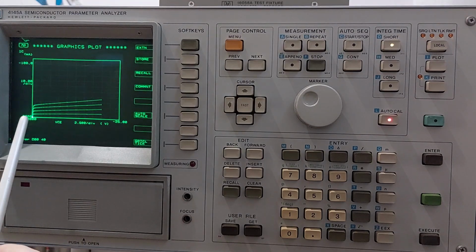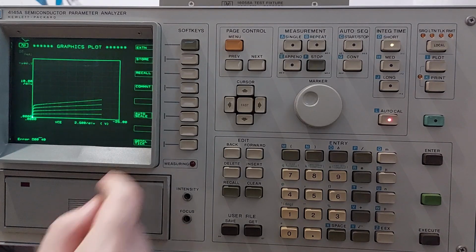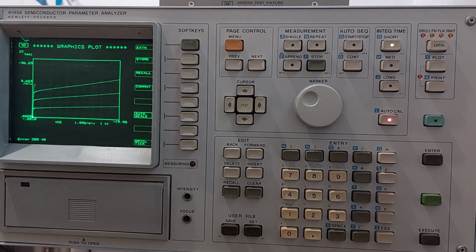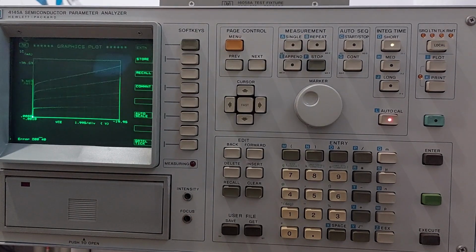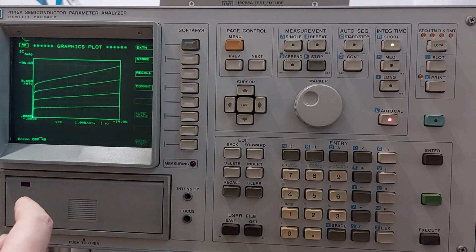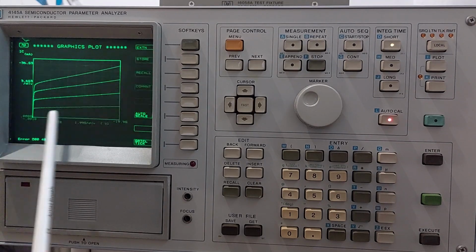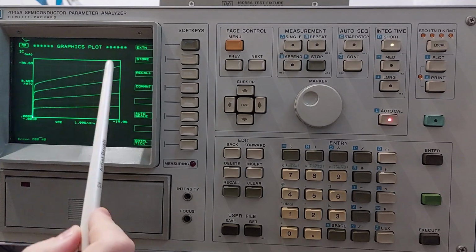Here you have your volt ampere characteristic of your PNP transistor. We can auto scale to see it better. So how to calculate DC current gain for this transistor? Well, you just need to divide collector current by the base current. So we know that our collector current is plotted on this axis, and the base current is basically presented in the steps, which can be visible here.